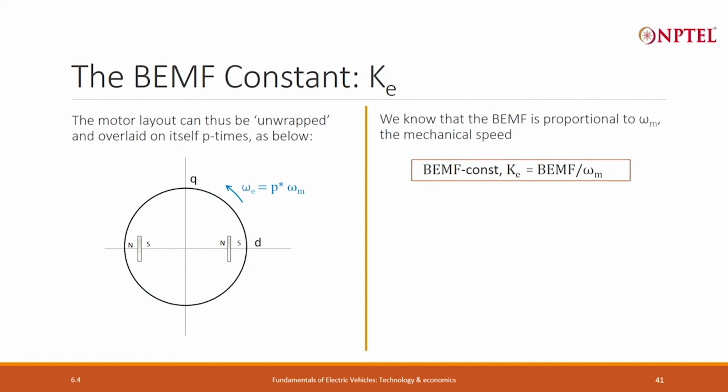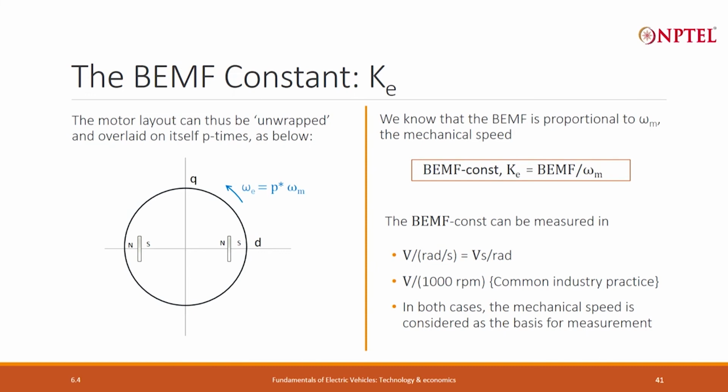So, this is a very important relationship. It is a fundamental label of a motor. When I want to compare one motor and another, the first thing I will look at is the back EMF constant. By comparing them, I will know many things about the motor. We will learn about that going forward.